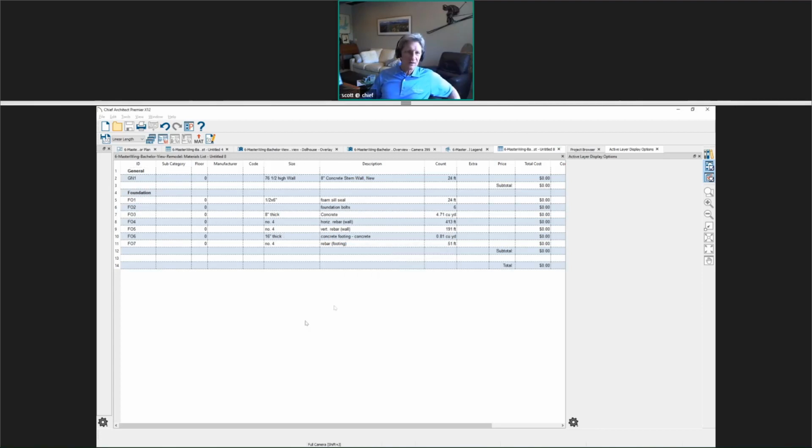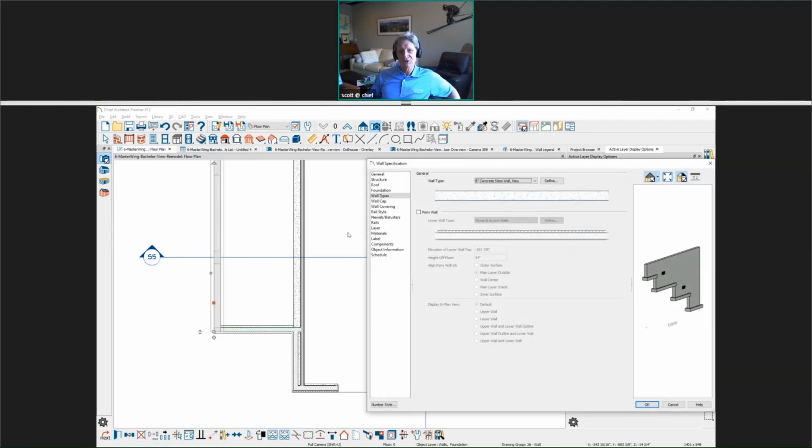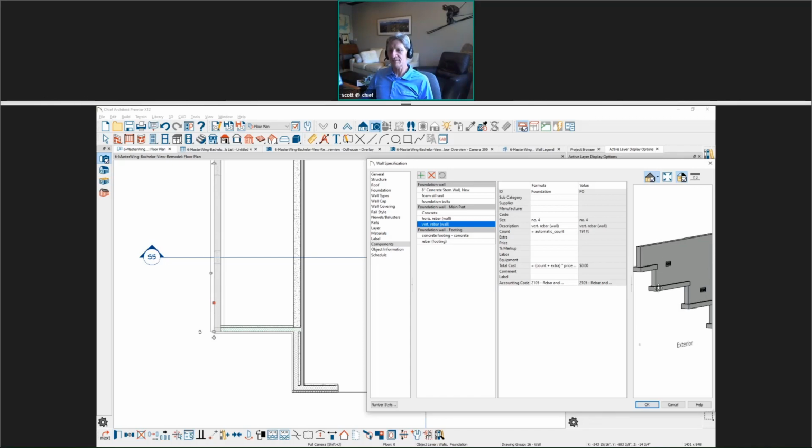And each one of those walls, if you look at the detail inside of the component code, if we went over to components and you look at how that is being calculated, here's your rebar for horizontal and vertical, and then you have the formula and access to control that inside of the dialog in here. And that's a stepped wall, so that's a little bit more complicated, right? But yes, you can control that in the wall dialog and components specifically right here. Okay, but there's no way to show it if you're on the slab? Not unless I draw it as a separate 3D object, yeah.